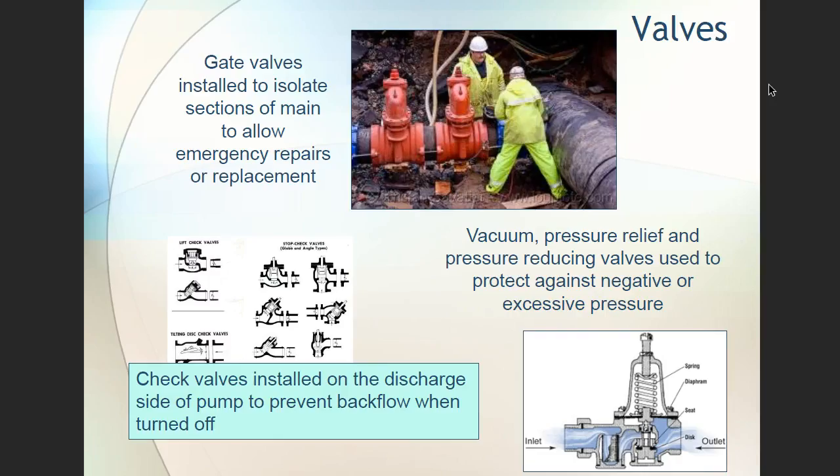Okay, look at the size of those valves. Those things probably weigh about 800 pounds each. So again, when you get into some of these bigger mains that you're working on, obviously those things are set in, normally with either a front end loader, chained up and dropped into place. But this is where some of the biggest danger comes for workers as they're working on pipelines in an excavated ditch: the dangers of getting fingers caught in there, all that kind of thing.